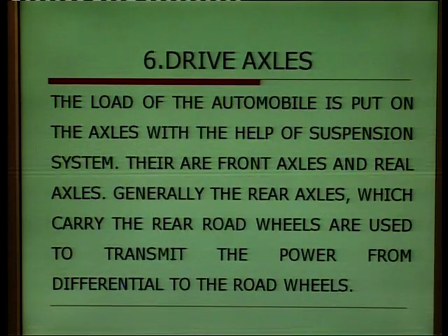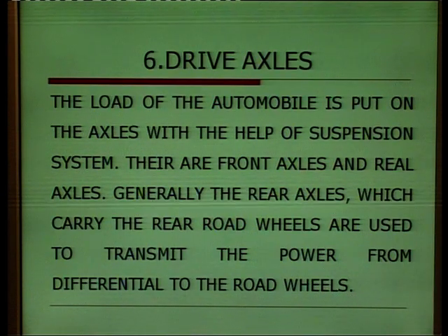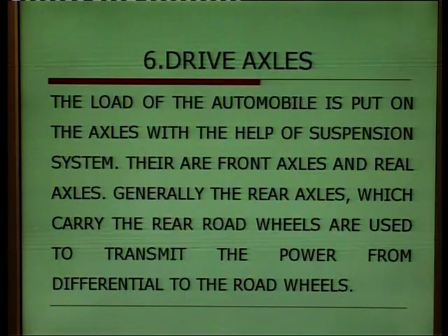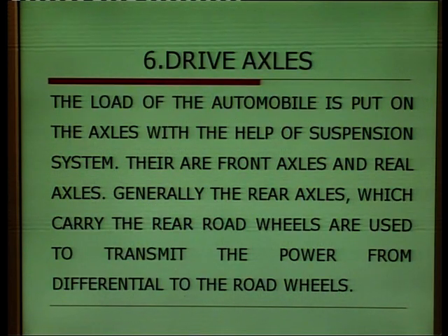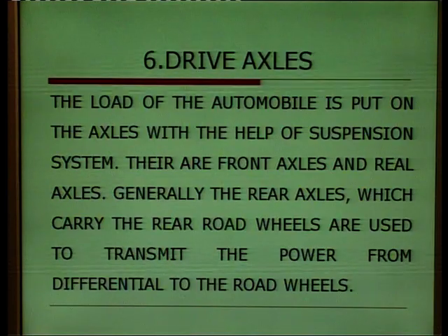Then drive axles. The load of the automobile is put on the axles with the help of the suspension system. There are front axles and rear axles. Generally, the rear axles, which carry the rear road wheels, are used to transmit the power from the differential to the road wheels.